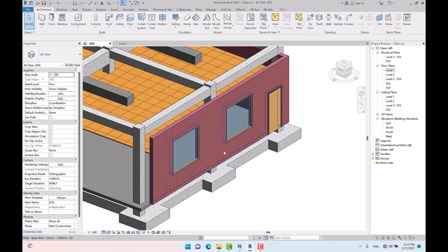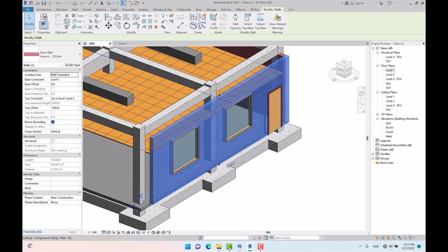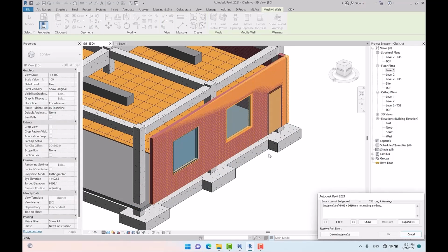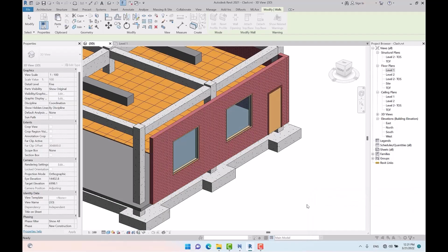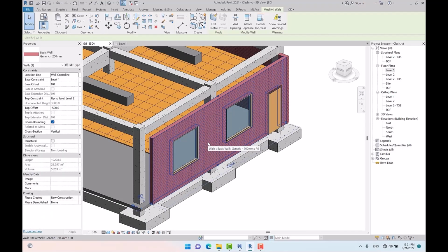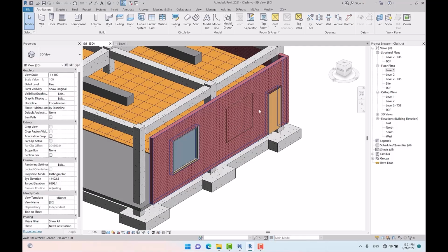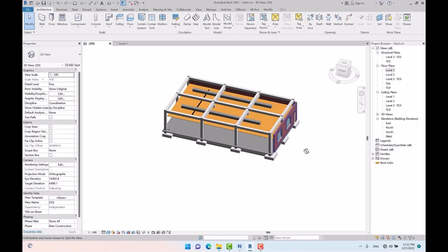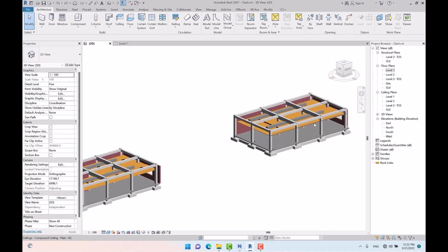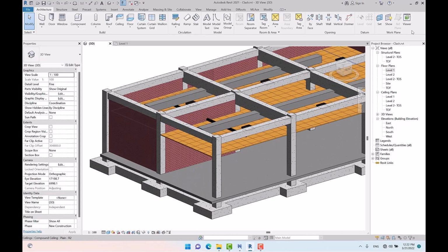Following that, we got some lights, but in the other model I want to make a copy of the selected wall this way, then I paste it aligned to the same place. Note that when you copy a wall or an object and then paste it aligned to itself, the doors and the windows will be pasted aligned to the same place. Here, as you can see, I got two windows. So practically here we got two walls which are overlapping each other.